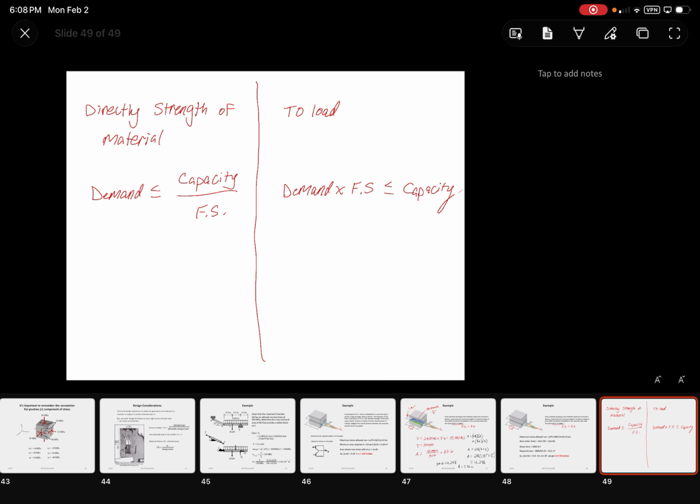In a lot of cases, in industry, if you're a civil engineer, you would call something like this a strength reduction factor, and then you would consider the factor of safety for loads a load factor. So if you work an internship and you hear load factor or strength reduction factor, that's what it means. It's just, are you using ASD or LRFD, which is how you are applying the factors of safety. And that's not necessarily explicit to civil engineering. I'm just talking from my own experience.